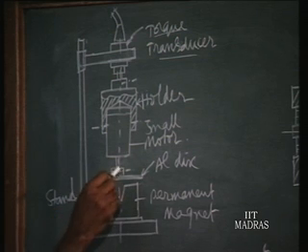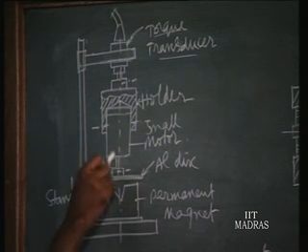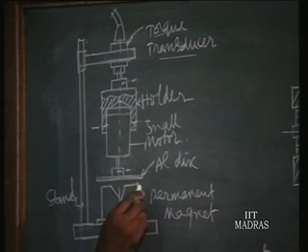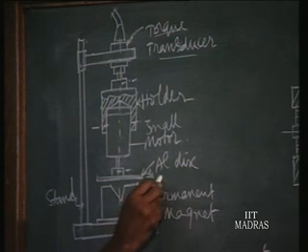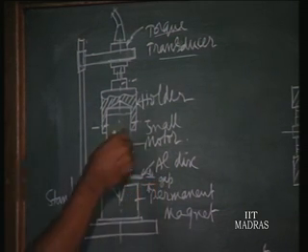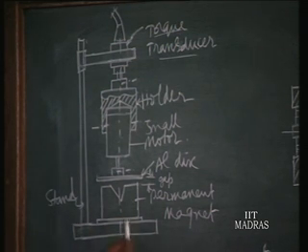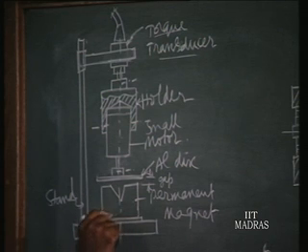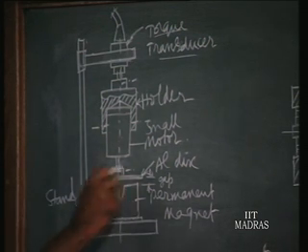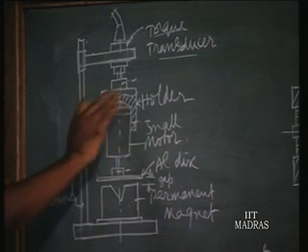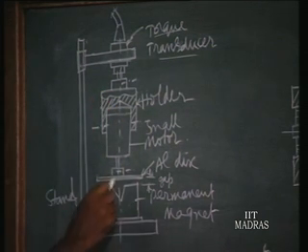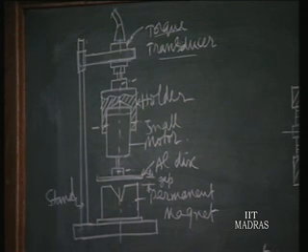Now different torques are developed in the rotating disc. The disc is fixed by a screw to the shaft of this motor. By adjusting this gap, we apply different torque on the system. That is what we learnt earlier, the eddy current dynamometer. By having different heights of this plate, we can change the gap, and then the torque is varied. Accordingly, the torque is registered by the instrument. And if we measure the RPM with another pickup, we can plot the torque speed characteristics of the motor.